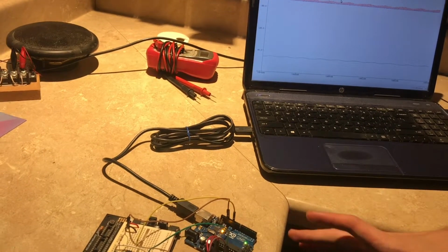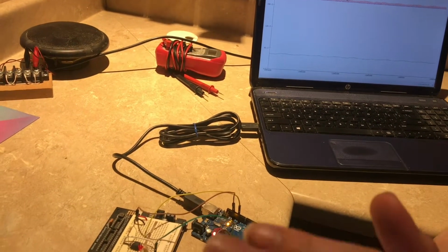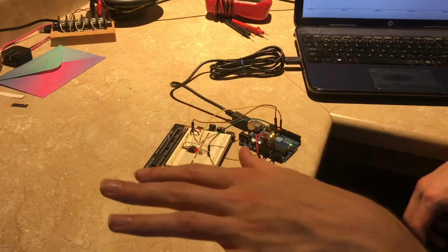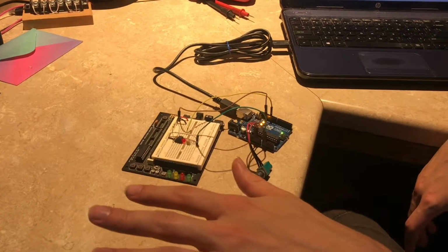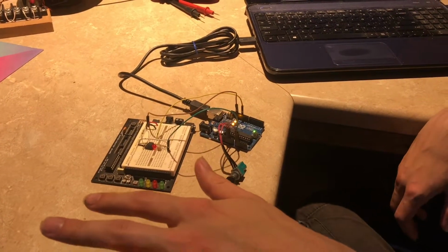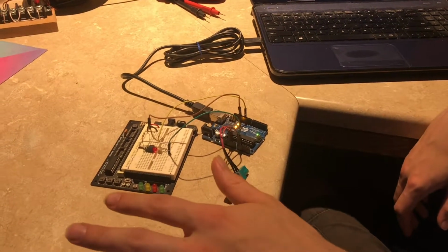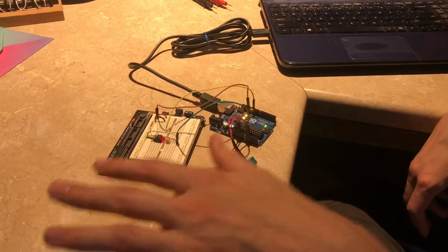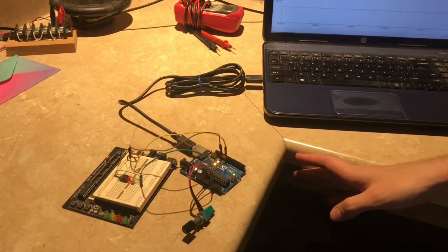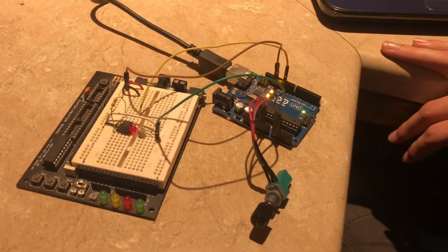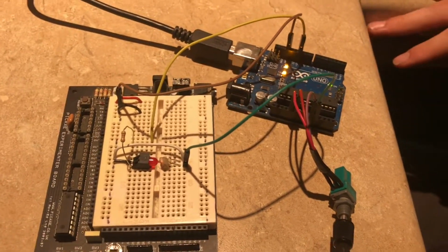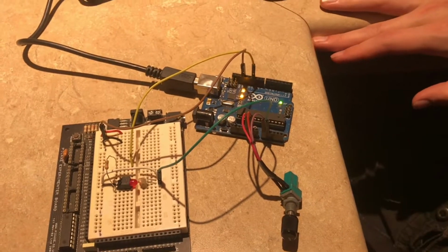If you have a remote control helicopter or a quadcopter, in order to get it to balance in the air, the set point of course would be that the aircraft should be flat, and the actual reading comes from accelerometers and gyroscopes on board, and then it uses the output to the motors to try to adjust the sensor reading until it reaches flat. And it's actually a very similar algorithm that I'm using here that you would see in like a quadcopter or something.